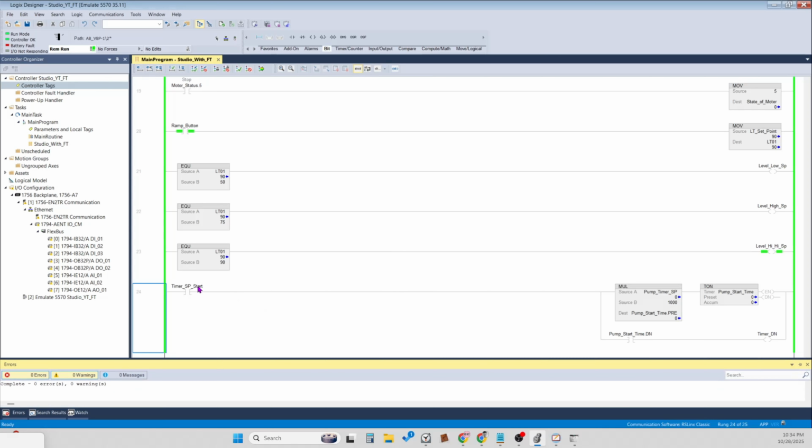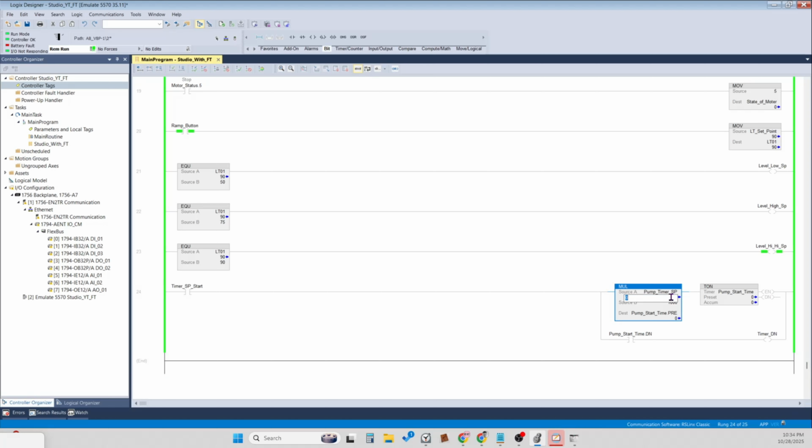So next thing, if we write here something, for example 20 should be multiplied with 1000. So you can see 20 into 1000 means 20,000, and the timer is also activated. The timer has started. After the timer is done, done should be energized.